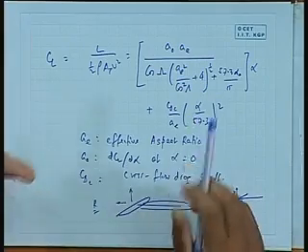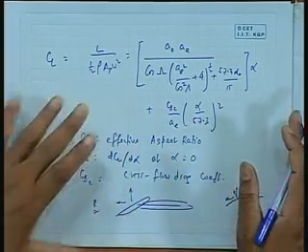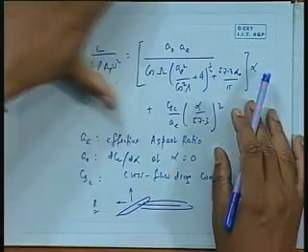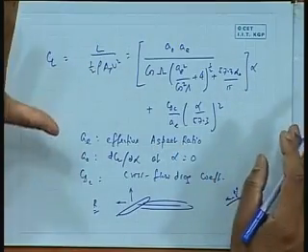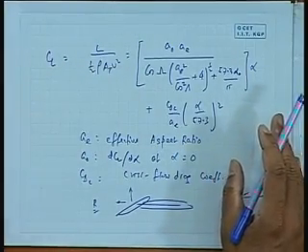Once you have this lift and drag for each section, then you can add them up. But a better thing that has been done here is that for a typical rudder section, the integrated lift and drag could be expressed by means of some empirical formula, which takes into account the geometric features such as aspect ratio and sweep angle, etc. This is only a question of applying a simple formula to a rudder, for design purposes.